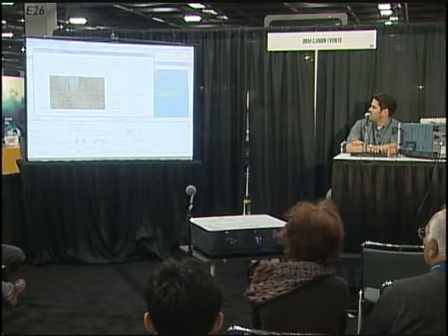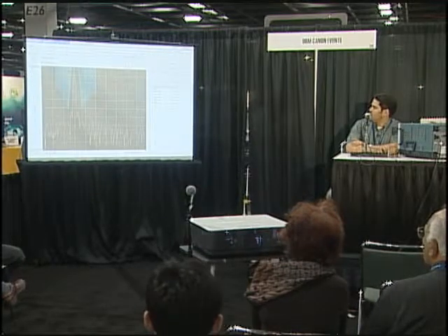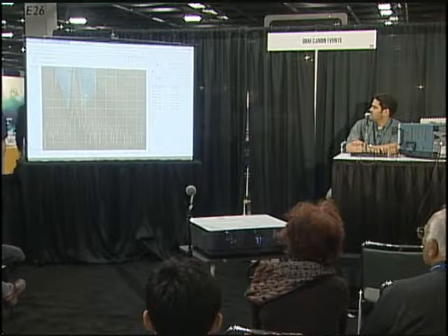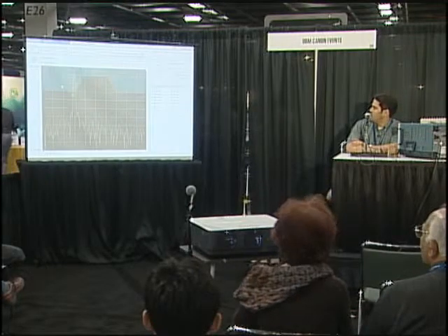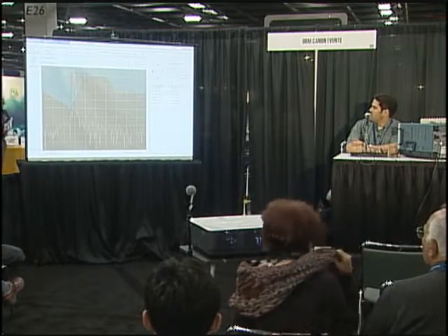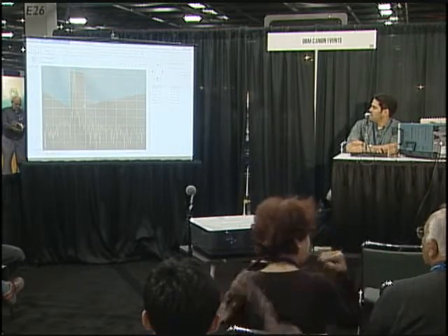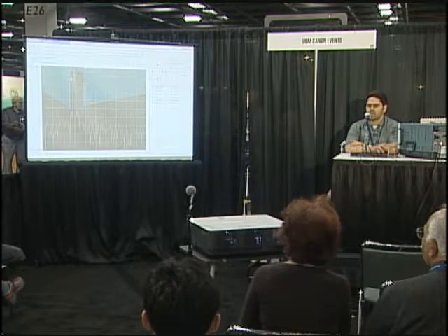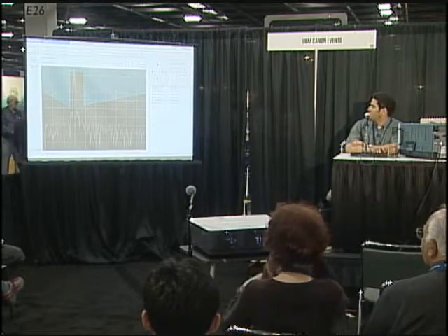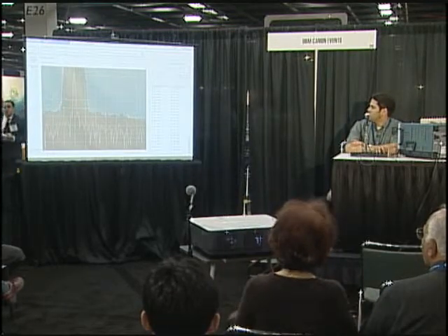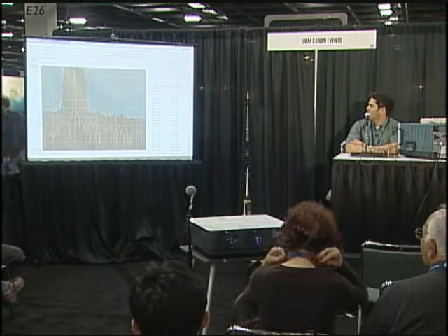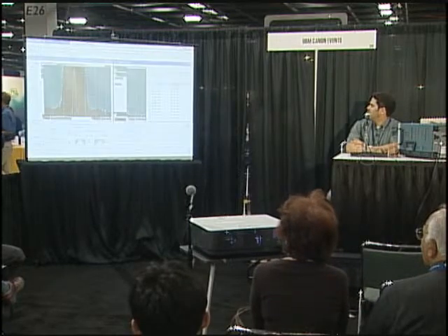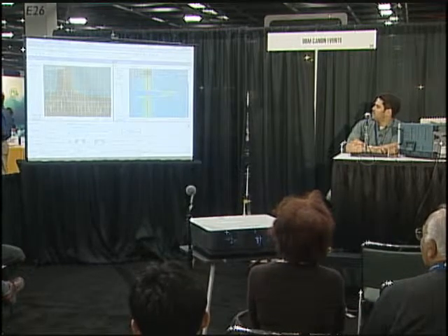You can go to the mask editor, and then you just add points, and then you move the points around, right? Like how we build this mask, for example, you could have just moved these dots around, and this tells the instrument, make an acquisition whenever the signal touches the mask. You can also do an auto draw that will just do the mask for you, and you can make it tighter or looser, right? So just close this, go back to where we were.